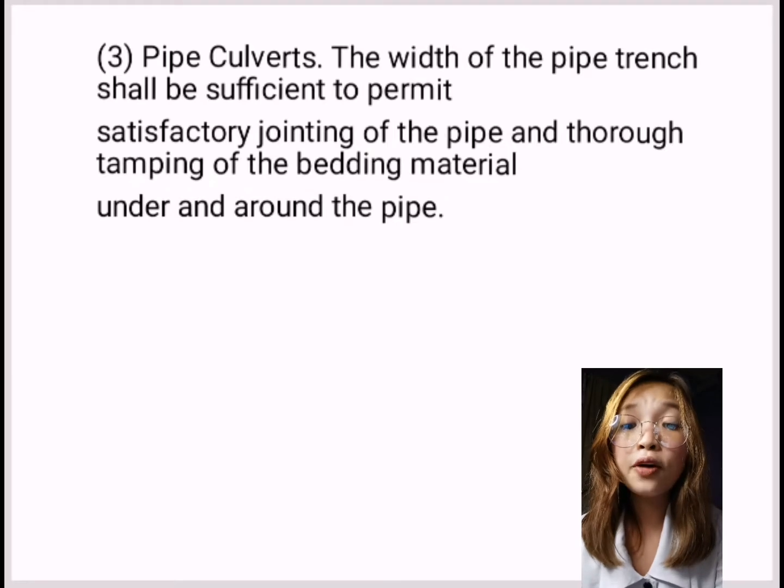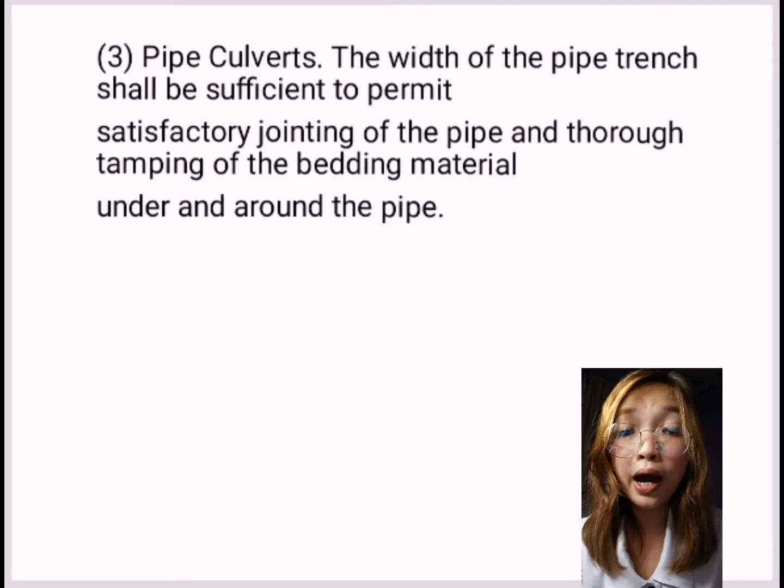So the width of the pipe trench shall be sufficient to permit satisfactory jointing of the pipe and thorough tamping of the bedding material around the pipe.